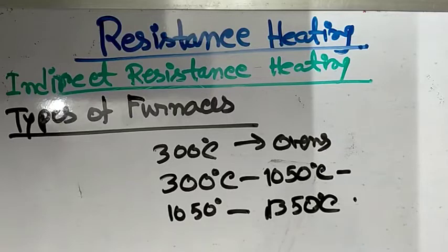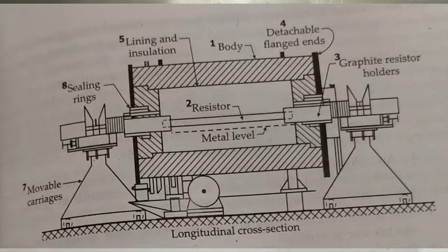If satisfactory means are provided to reduce the rate of oxidation to a minimum, to compensate for increased resistance as wear takes place, and to replace the graphite resistors easily and quickly when their useful life is complete, full benefit can be taken of the advantages of resistance heating over a high temperature working range. The rocking resistor furnace, as manufactured by Messrs. Birlec of England using graphite resistors, you can see in this picture.